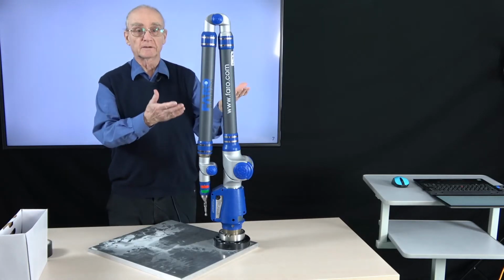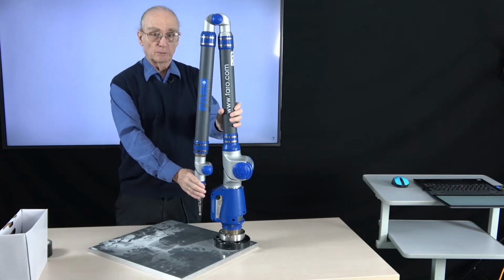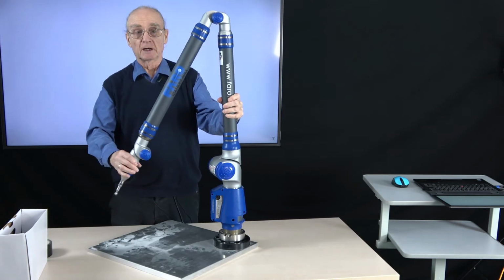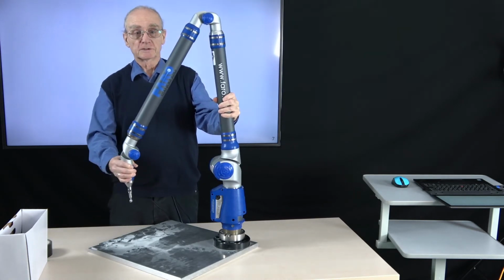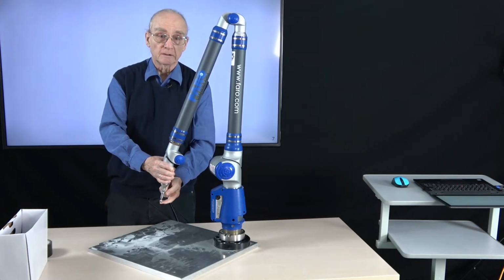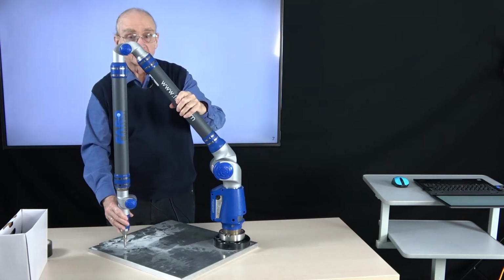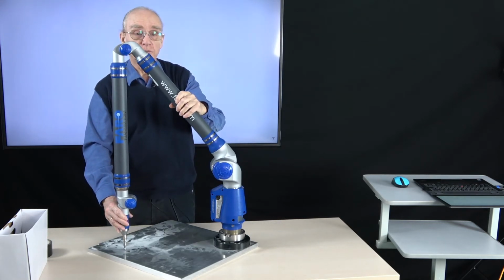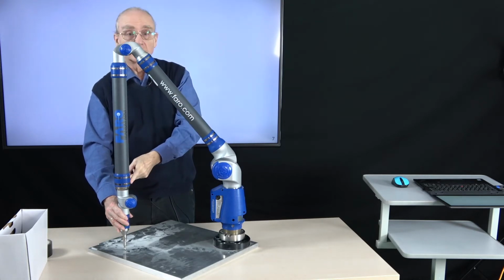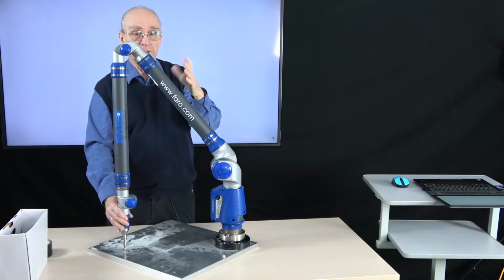So what you see here is a measuring arm. It's a passive robot because I control, as a user of this measuring arm, the motion. And you see I can move this measuring tool here, which is a ball, and touch, let's say, the surface here, and then the system is measuring the angles in these joints between these different links of the robot arm.